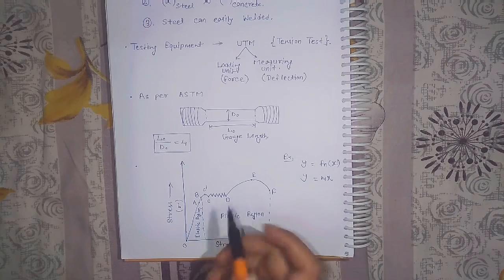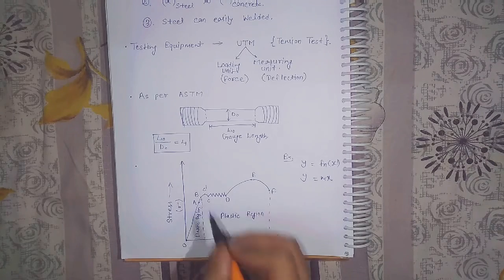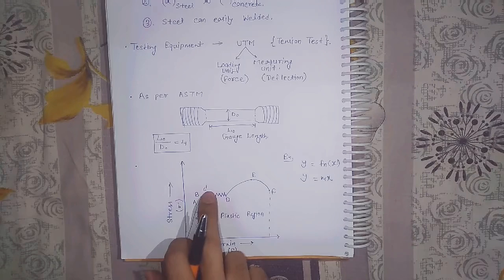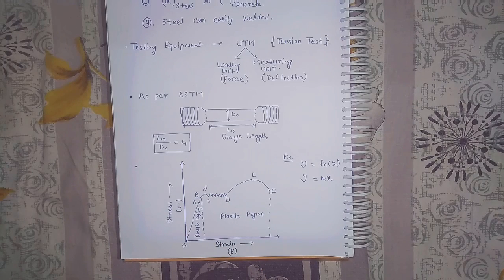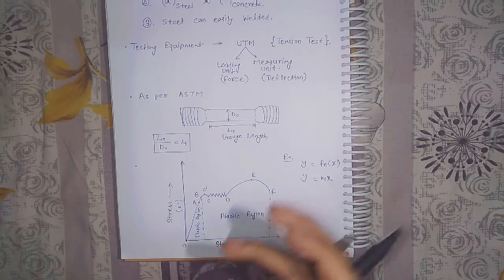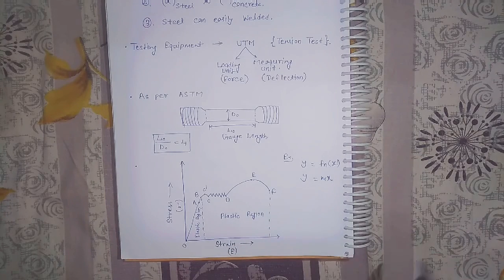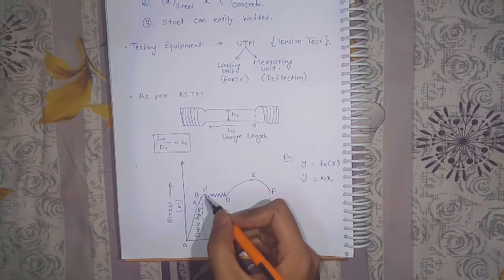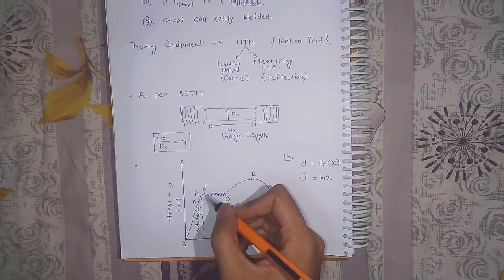In practice, we take the yield point as the lower yield point. Why do we not choose this value C dash? C dash is not a fixed value. It is a fluctuating value. It is a long theory which is discussed in a different lecture. It is due to the slipping of molecules, slipping of carbon molecules or whatever the material contains. That is why this point is fluctuating.